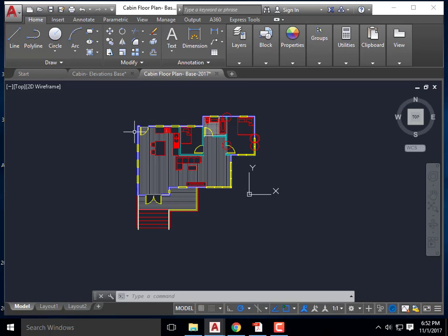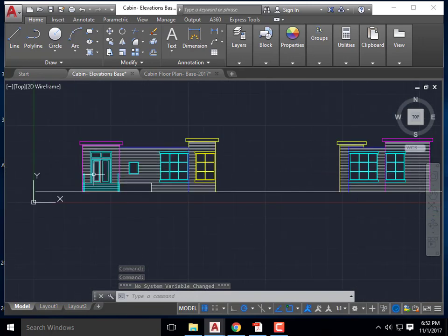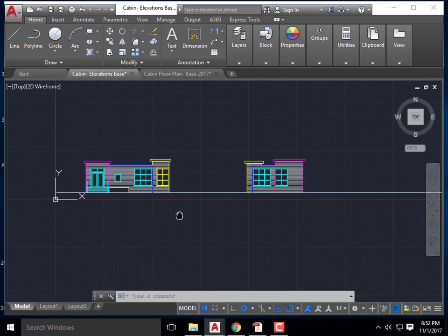Well, if I want to reference something else that I've drawn in another file, you can set up an XREF. So basically, it's a link from one file to the other. So what I'm going to do is, and I'd recommend if you want to follow along with me, you can do that. I have two things. I already have a couple elevations from last semester that kind of show a basic understanding of what it is that I'm going to be drawing.